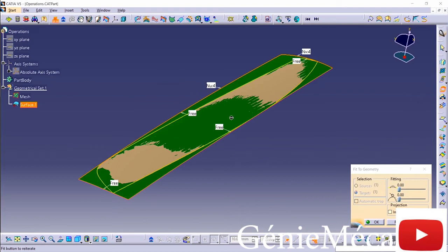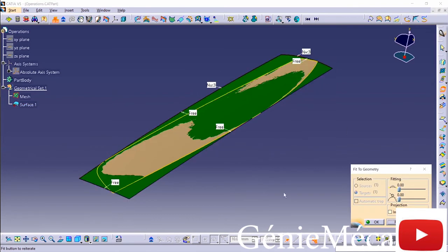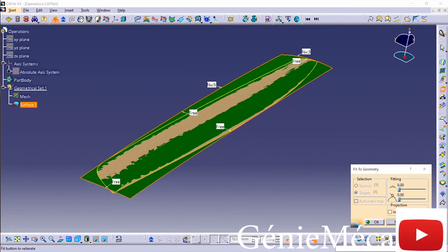And with that, I have the ability to increase or decrease the amount of math, the NURBS math, by right mouse clicking on one of those little flags, and then reimposing the surface onto that mesh. If I just simply click on that number, you can see it just goes up and refits it. So I may be getting closer, pushing it further away, creating undulating surfaces.